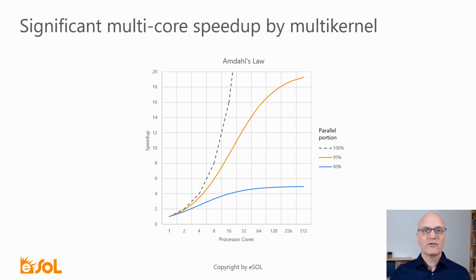Today's applications that were developed on RTOSs with old microkernel architecture have a reduced parallel portion. That wasn't a problem with a single core and not a huge problem with dual cores. However, if you are using quad or more cores, you will never see much acceleration with such RTOS architectures. If you can increase the parallel portion on an 8-core system from 80% to 95%, you would see an acceleration of 80%. That means with only 14% improvement in the parallel portion, the computing power would almost double. On 32-core hardware, the difference would already be a factor of 3.